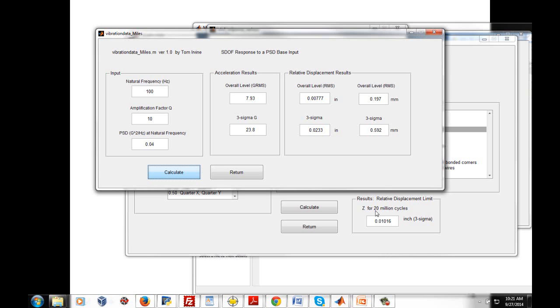Now, for my design rule of thumb, here's what I'd recommend. My ideal avionics box has a very stiff circuit board inside, but on the outside of the box housing, that same component is mounted via soft isolators or bushings or grommets, whatever you want to call them. That will take the natural frequency of the box itself down to a very low frequency, so it will attenuate the shock and vibration that propagates into the board. But once that attenuated shock and vibration does propagate into the board, that board is so stiff that its relative displacement relative to that incoming excitation will be negligibly low.